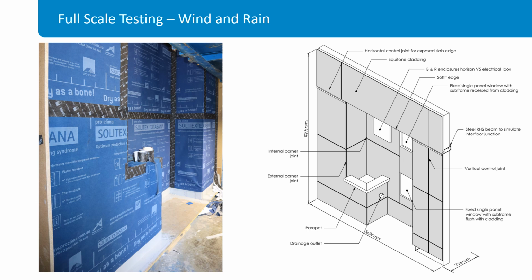So when we do a full-scale facade test, we're not just testing a flat facade. That's too easy. What we need to test is all the details. So we need to address this structure here, which includes the details of how to connect into windows. It includes parapet details, box gutter details, penetrations like pipes and how the WRB needs to connect into that, details at the base of the wall, at the top of the wall, and possibly in some circumstances the WRB needs to wrap around soffits.